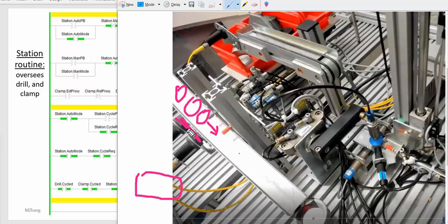The part present will never be off, right? Because there's no unload for that, right? Same thing for here. This sensor over here, that'll be the part present, the trigger start for station 2, right? But once station 2 transfers to here, at the same time, station 1 may already feed the next part in there. So while the arm is doing the transition, the part slides down here, the part present is on again, right? So that will be the other challenge.